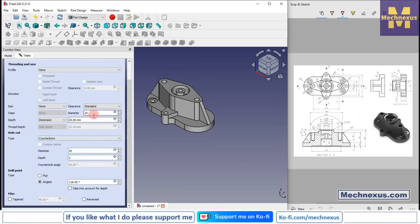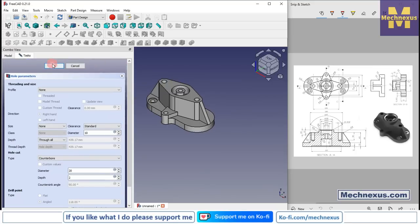So here drill is of 10 mm, and here in the dimension we can also set it to through all, and diameter 20 for counter bore and 2 mm depth, and click on the OK.